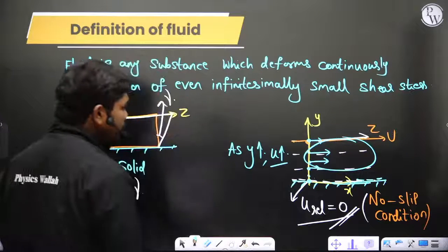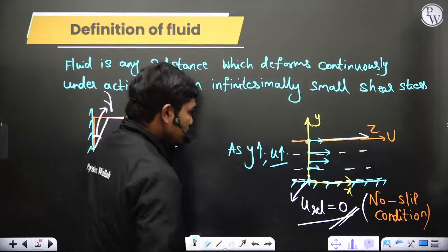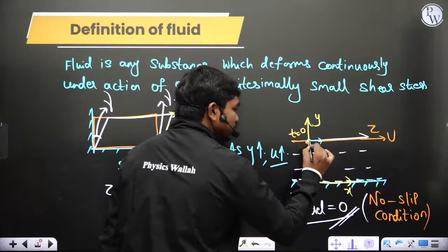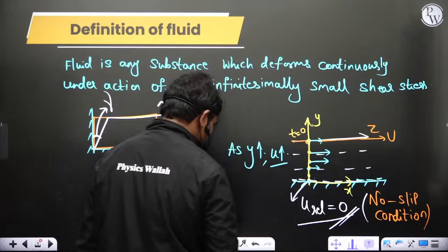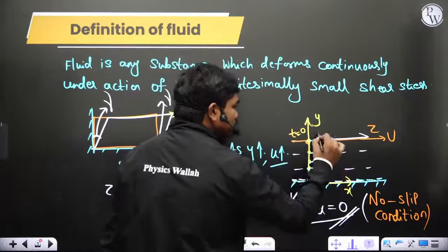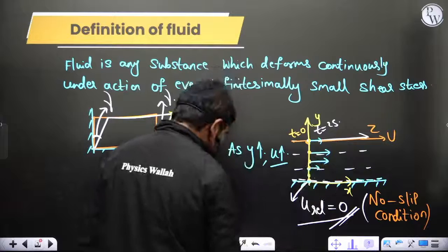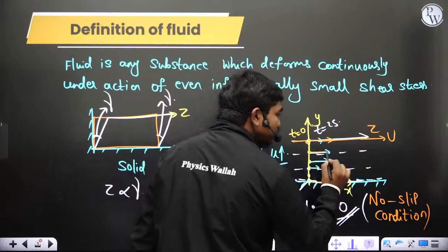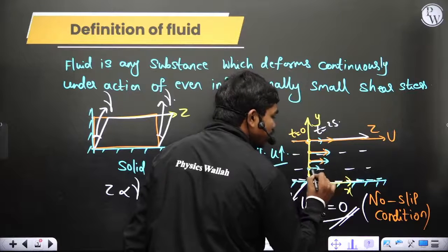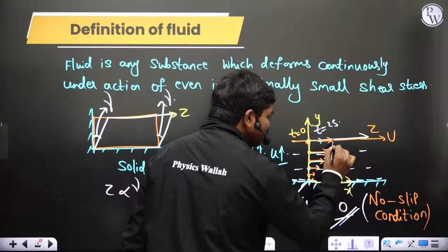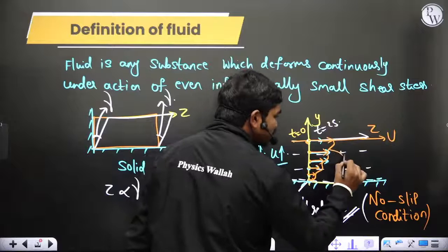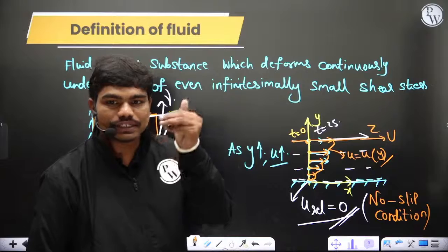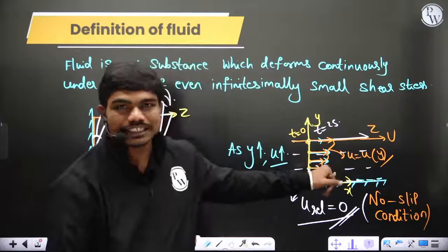Viscosity. Now if you see in this case, coming to one important understanding, this is at time t equal to 0. If these are the positions of the particles, then at some time t equal to say 2 seconds, definitely one thing is very clear: this particle moves a little far, this particle moves slightly less as compared to this, and like this. So you will have a certain velocity profile which changes with respect to y. Means as y changes, this u will also change.